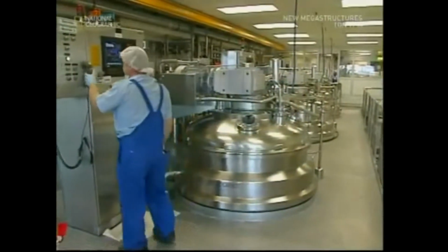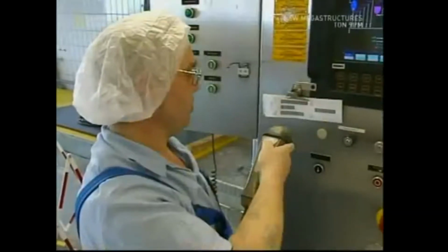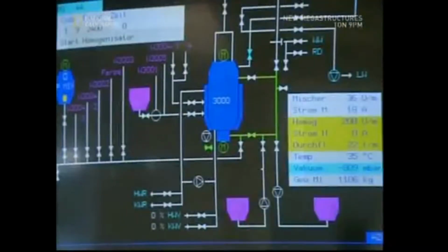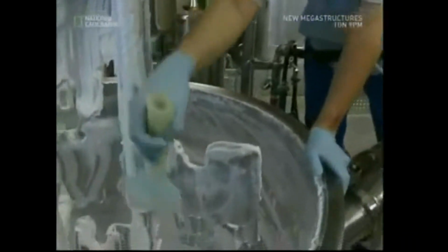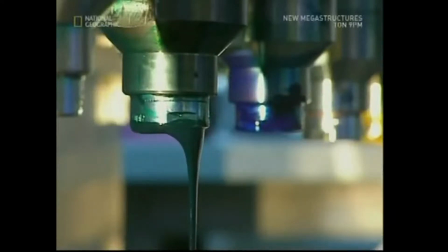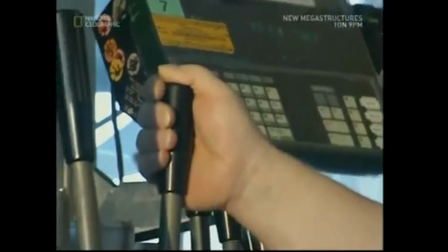The main principle utilized in the manufacturing of toothpaste is mixing. The ingredients of a toothpaste are subjected to mixers where temperature and humidity are closely monitored. The composition of toothpaste is sorbitol, calcium carbonate slurry, carboxymethyl cellulose thickener, preservatives, methylparaben, sodium saccharin, sodium monofluorophosphate, sodium silicate, sodium laurate sulfate, and flavor.